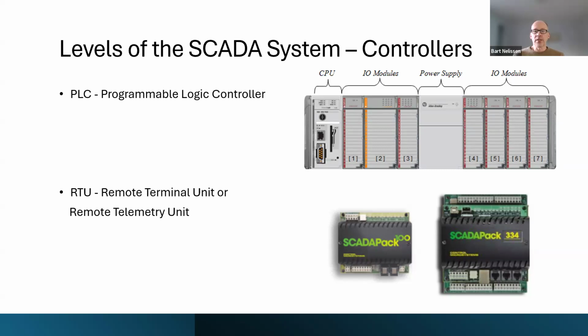The first main component of a PLC is what we call a CPU. That is called a central processing unit. And that's really the brains of your PLC. That's where the program resides that is written by a programmer. And that's what actually performs all the logic. Then we have the modules. And the modules are called I/O modules. And the I stands for input, and the O stands for, you guessed it, outputs. So I/O modules are the components of a PLC that are physically wired to the devices out on the plant floor.